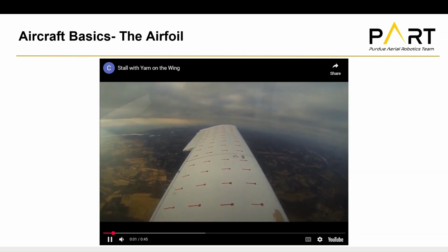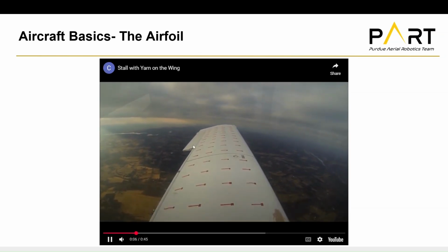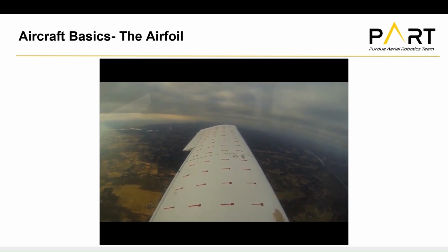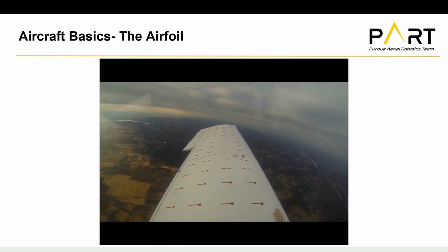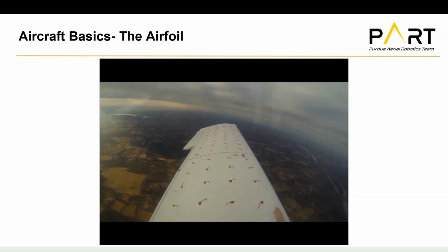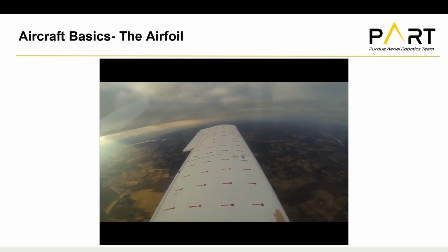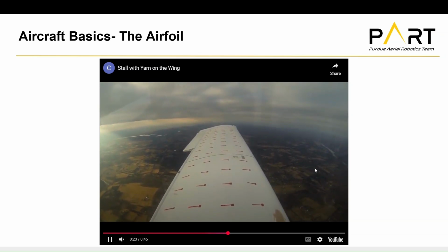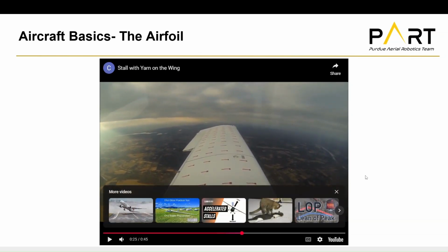So you'll see, right? Laminar airflow. Those tufts are very straight. Looks very nice. He's got his flaps down here. That's why there's kind of that gap in the wing. And he's going to pitch up. He's pitching up right now. You hear that stall horn, which tells you when you're about to stall coming in. And those tufts all of a sudden become very turbulent, right? Because the airflow is separated and the plane pitches down. So you can kind of see how the wing stalls out there. So some cool stuff to see.